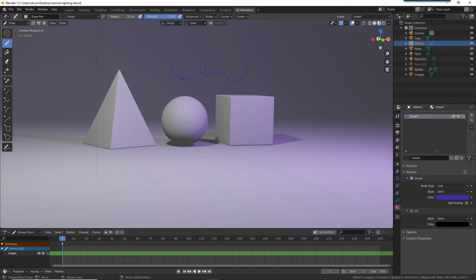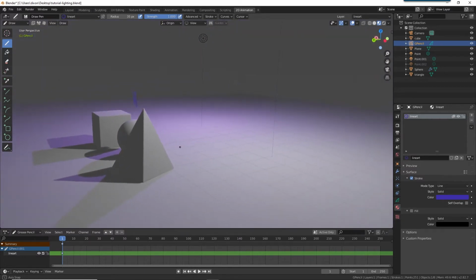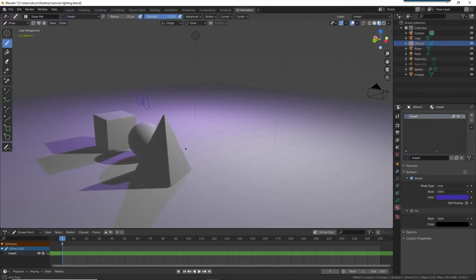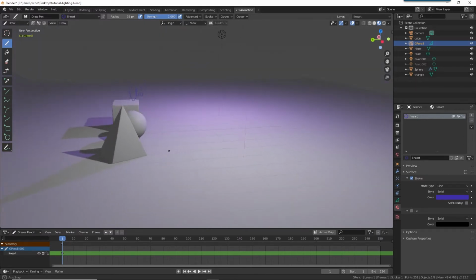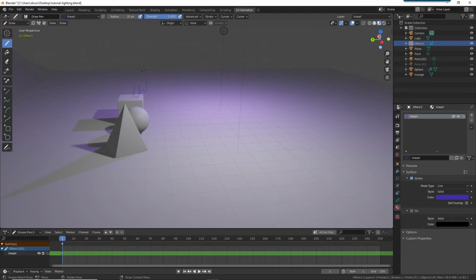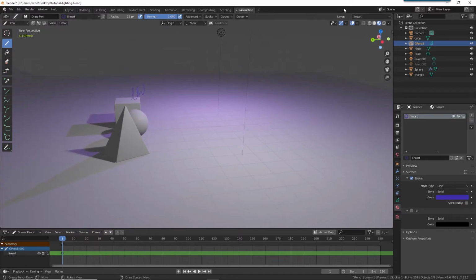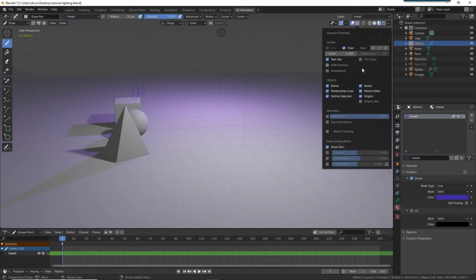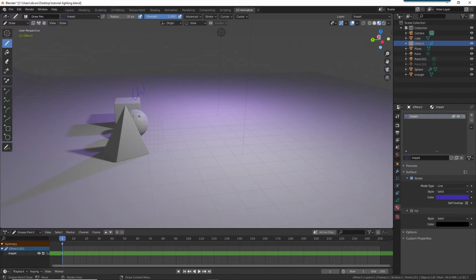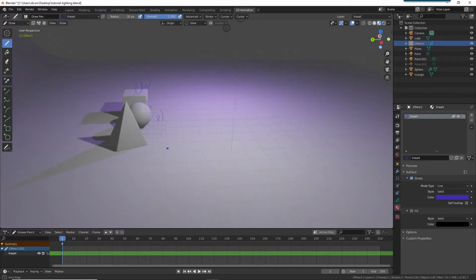Now, when you pan, the line is on a plane in 3D space. And what we want to do now is look a little bit more at how that works. So, first of all, if you go to Overlays, at the bottom here you'll see there's an option Canvas. And when you select that, you can see this invisible canvas, this magic canvas appear. And when you draw, what happens is the pen paints onto that canvas surface.